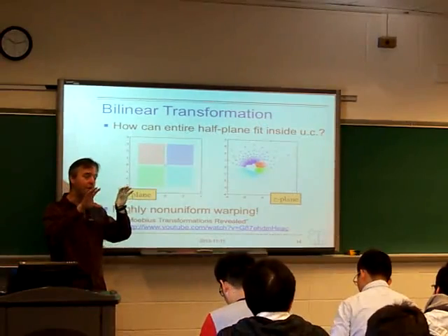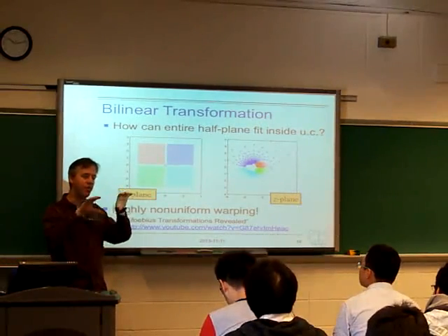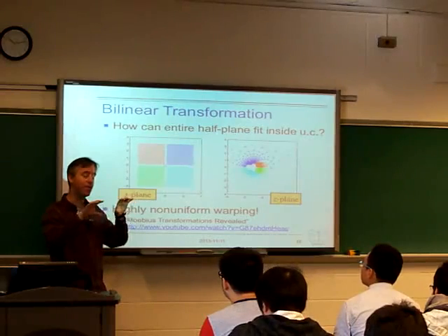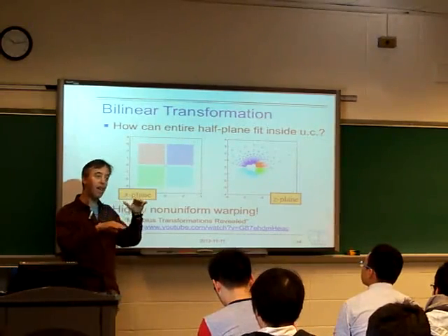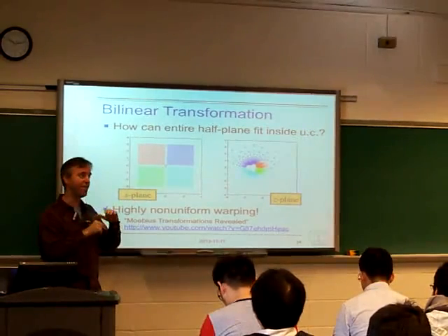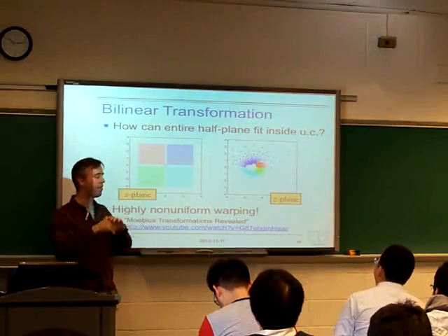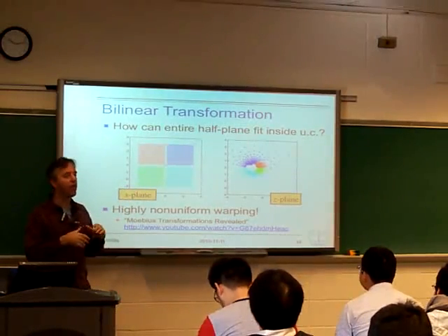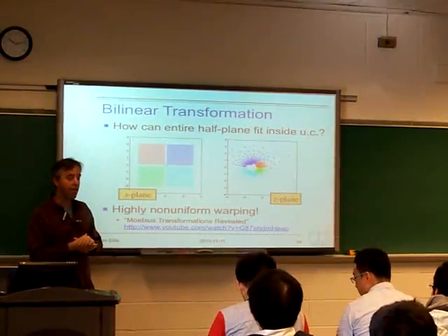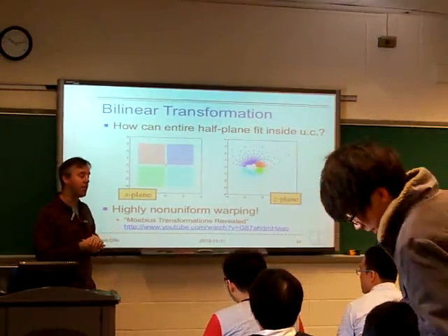If we can make all the ripples the same depth, then that's what we're looking for. That's going to optimize the largest depth of any ripple, right? We're balancing them all, so we can't reduce any of them without increasing the overall bound. Very often that's the criteria we want to achieve in practice with these kinds of filters.